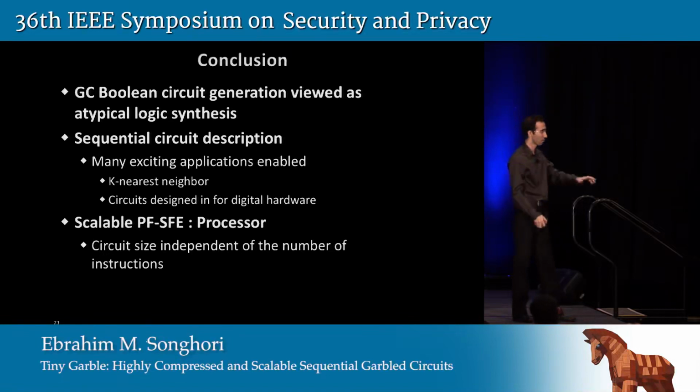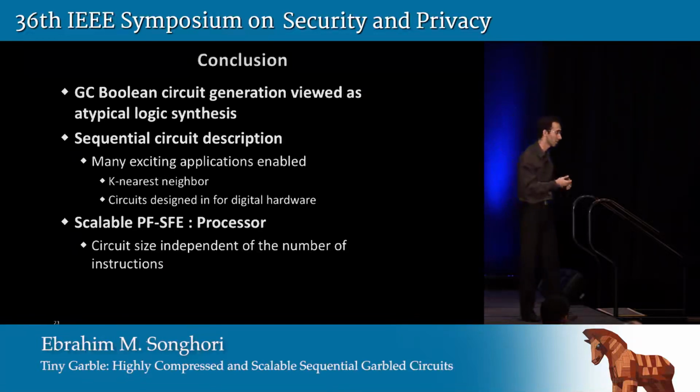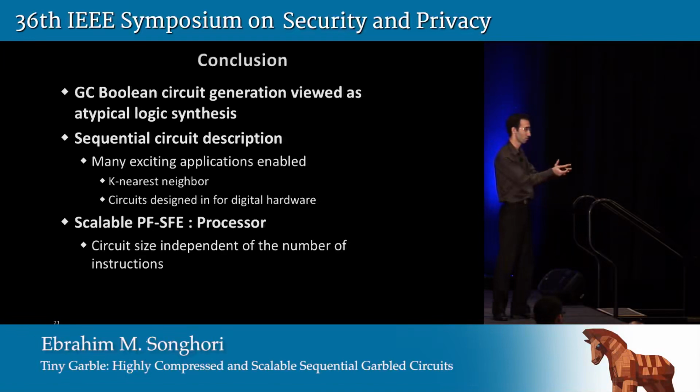We sweep the number of foldings of the circuit, or the number of sequential circuit iterations we need to evaluate. We sweep it from 1 to the maximum, and we find out which one is better. The size of the circuit will definitely reduce, and also the number of non-XOR will increase because of the asymmetry. If it doesn't have asymmetry in its loop, it will be static. So it actually depends on the function. We cannot ask those tools to do it for us. We need to do it manually.